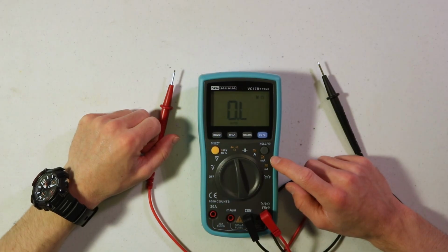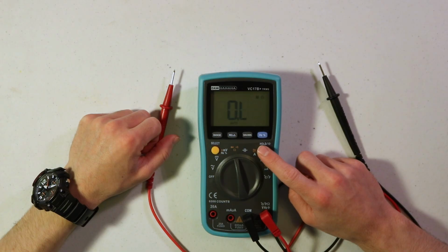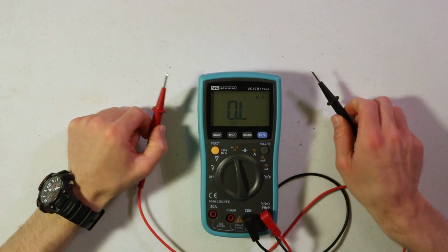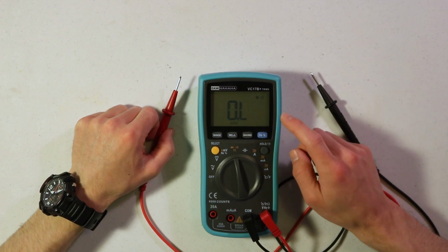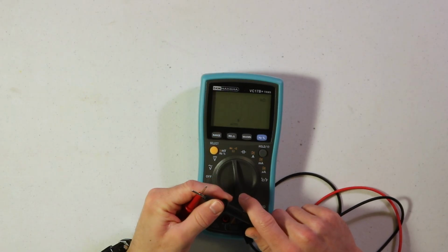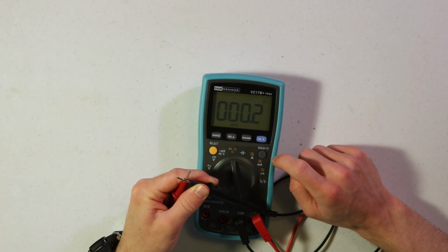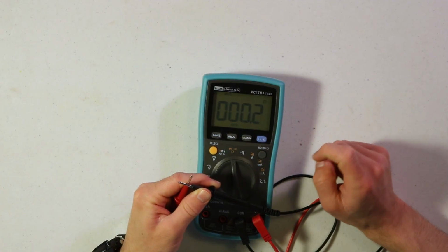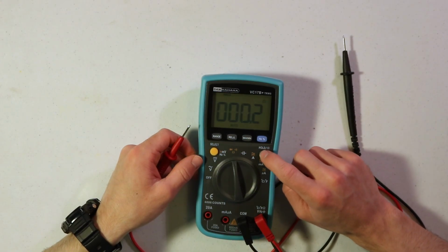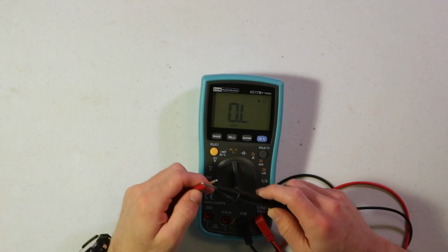The last thing to notice with the multimeter is the hold button. And all that does is it just grabs the value that you currently have on the screen, and it freezes it there so that if you stop measuring it, then it still stays there. So let's say that I'm measuring resistance again, I touch these across each other, and I get some value here. Rather than continuing to hold that on there, I can just press the hold button, and now I can separate these and the value stays there. And if I press it again, then it just goes back to the live value.